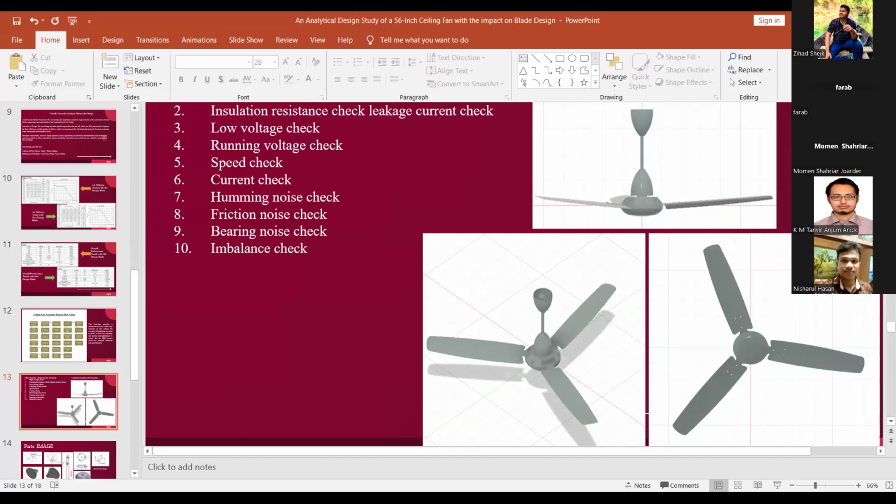So this is the toolpath we created in Fusion 360. For creating the toolpath, we initially fixed the setup, I mean the alignment. Then we created the adaptive clearing, then the pocket clearing, contour clearing, and finally 2D pocket clearing.